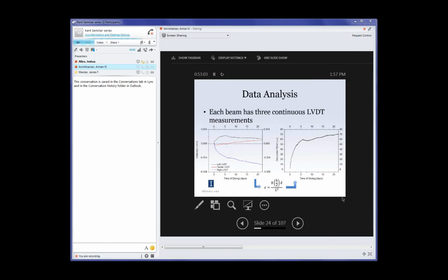Because you see some of the negative numbers, but how do you know that would really happen? Again, it would be an assumption of an extremely rigid case, but more likely than not, when it starts to revert back, the edge of the slabs would start to actually deform the base and not have as much lift in the center of it. Oh yeah, like in a pavement setting. Right.